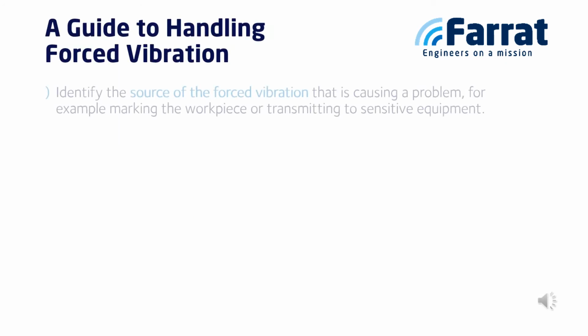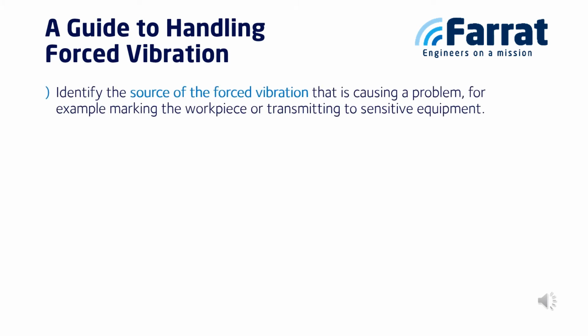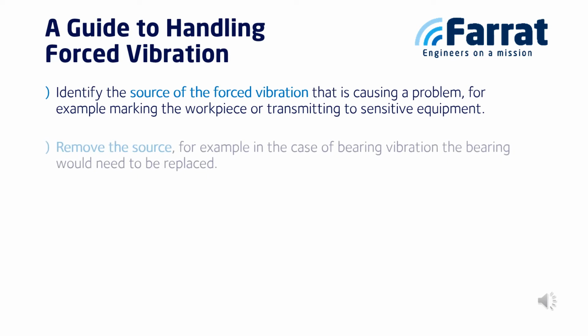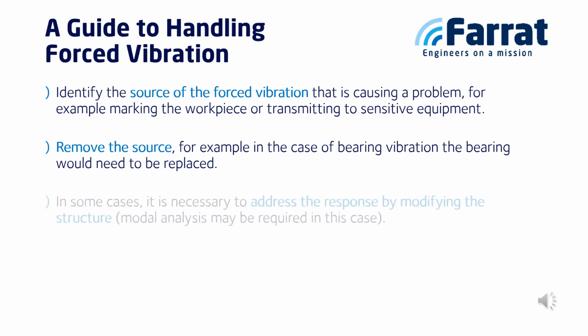As a simple guide to handling force vibration, we advise that you first identify the source of the force vibration that is causing the problem. This may be marks on the workpiece or transmission of vibrations to sensitive equipment. Then you should try to remove the source. In some cases, it may be necessary to modify the structure, in which case a modal analysis will be required.